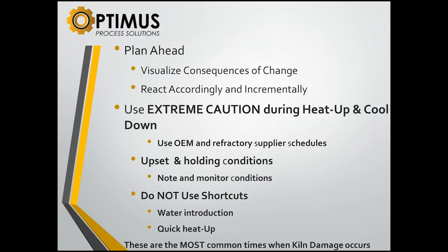If you try to start up too quickly and do not allow a long enough heat up, you will not soak the heat into the refractory, and you will spend much more time, and you will operate less efficiently for a period of time until that initial heat is within the refractory itself. You need to be very careful with upset and holding conditions. Note and monitor the conditions that you see, especially refractory temperatures.